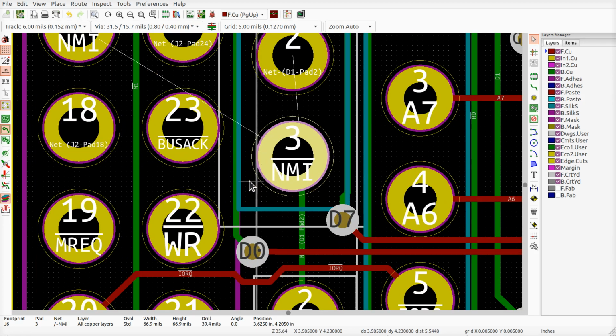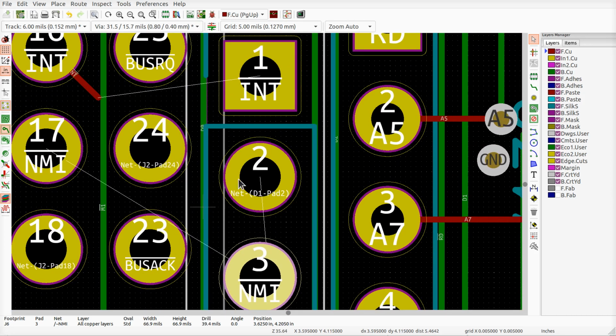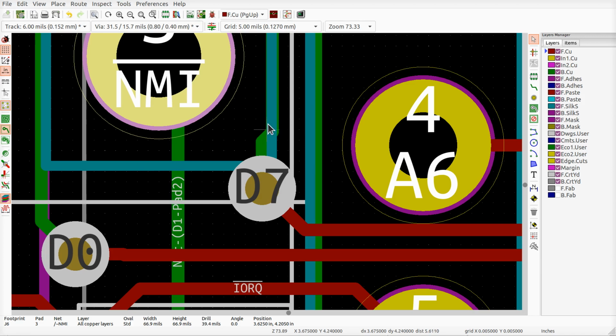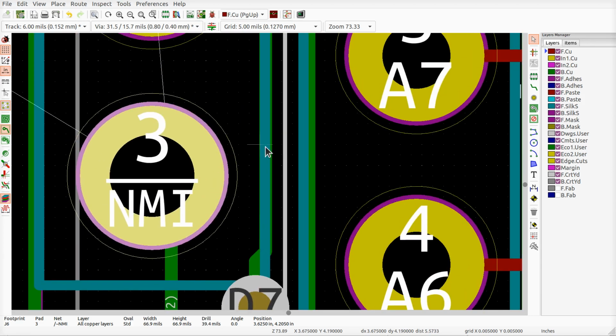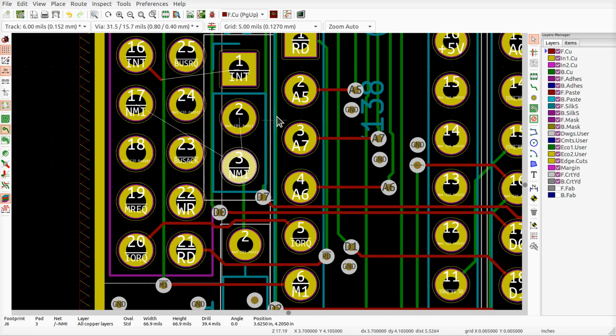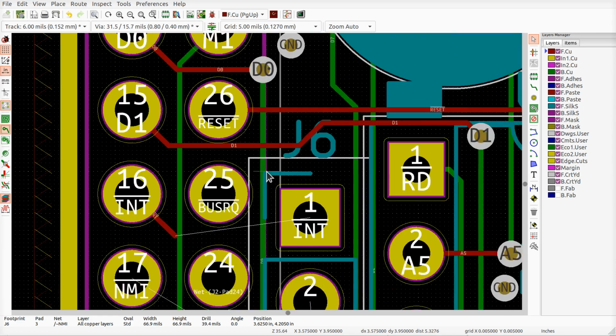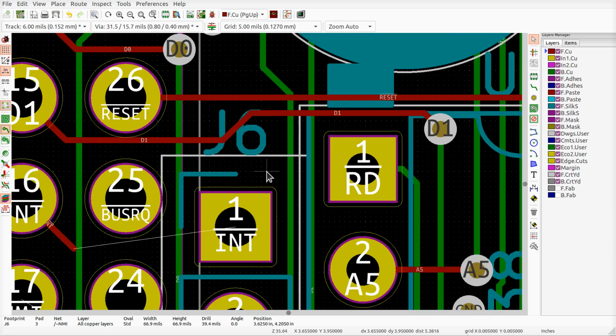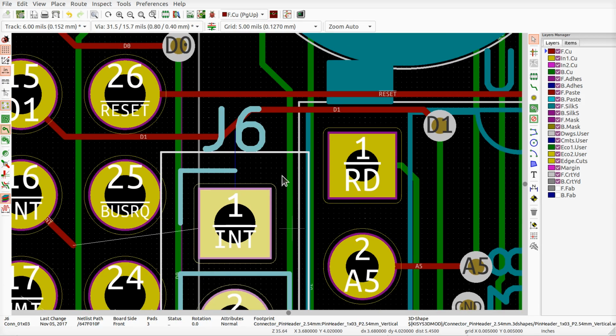But my experience is that you can actually see the silk screen around the base of these headers as well as on the socket housings. And therefore, as long as these drawings of the silkscreen outlines are separate from each other or overlapping, coincident, then I think we're going to be okay.